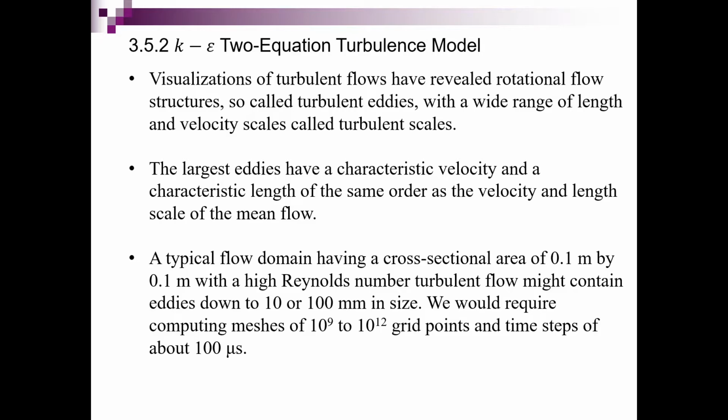For us to do simulation on turbulent flow, we need to make sure that the mesh that we build is very fine so that we can capture it, because as mentioned, the range of the characteristic length is very wide, from very small until very big. So to make sure that we capture all of the vortical structures from the small until big, we need to make sure that the mesh is very fine.